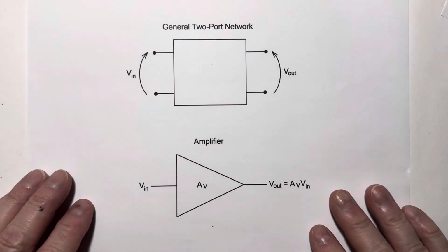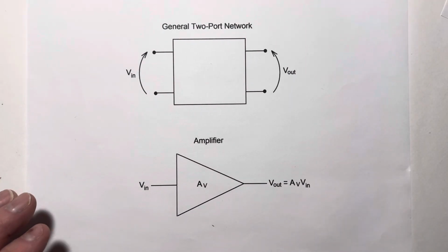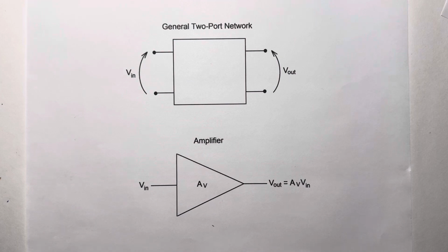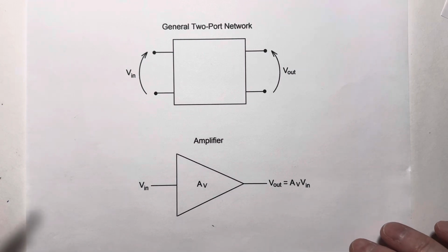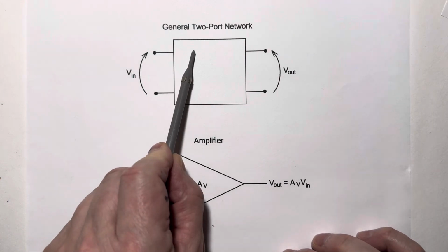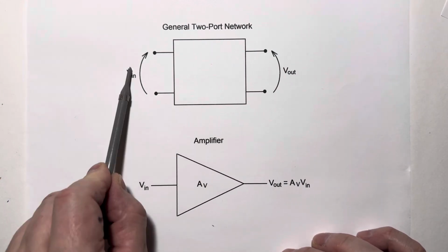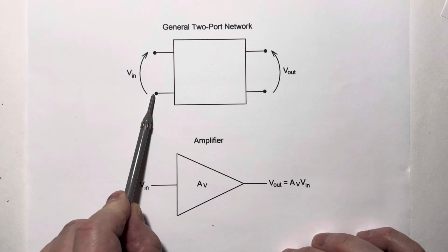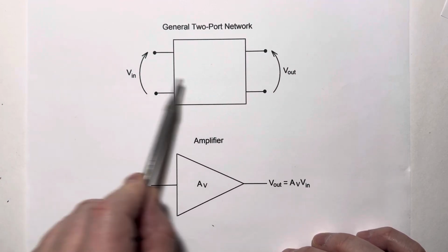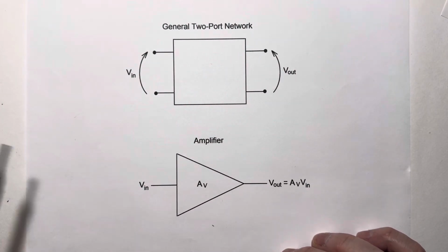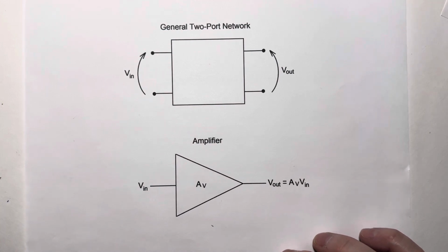And finally, before we end this video, I wanted to relate back to something I mentioned previously in the Thevenin's theorem video, and that was the concept of ports. Now, the voltage divider could be considered to be a 2-port network. We might have a divider inside this black box. It's got 2 input terminals, 2 output terminals, so the input and the output are considered ports.